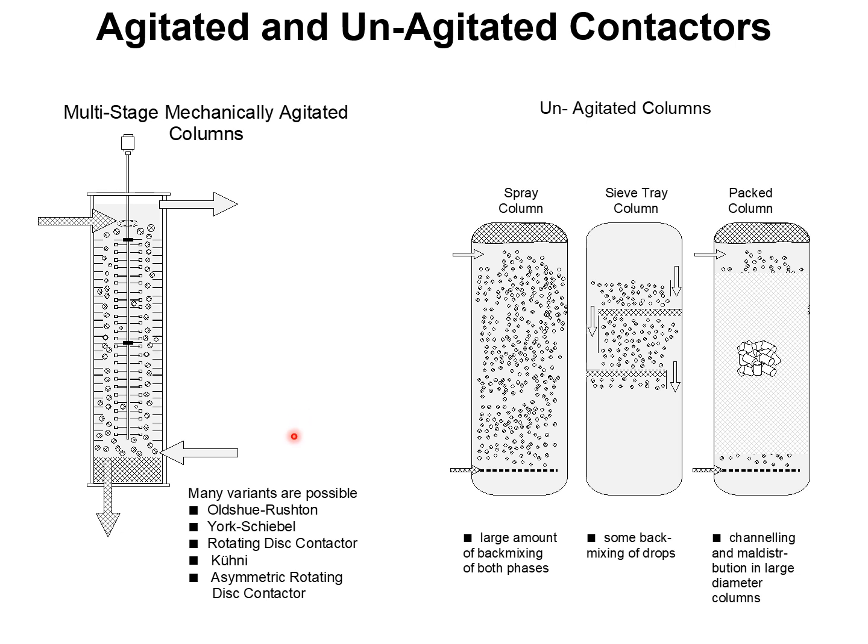With increased rotational speed, the drops become smaller in size. Therefore, there is more area per unit volume. But on the other hand, smaller drops tend to be rigid and stagnant, whereas larger drops are more mobile and afford higher mass transfer coefficient.